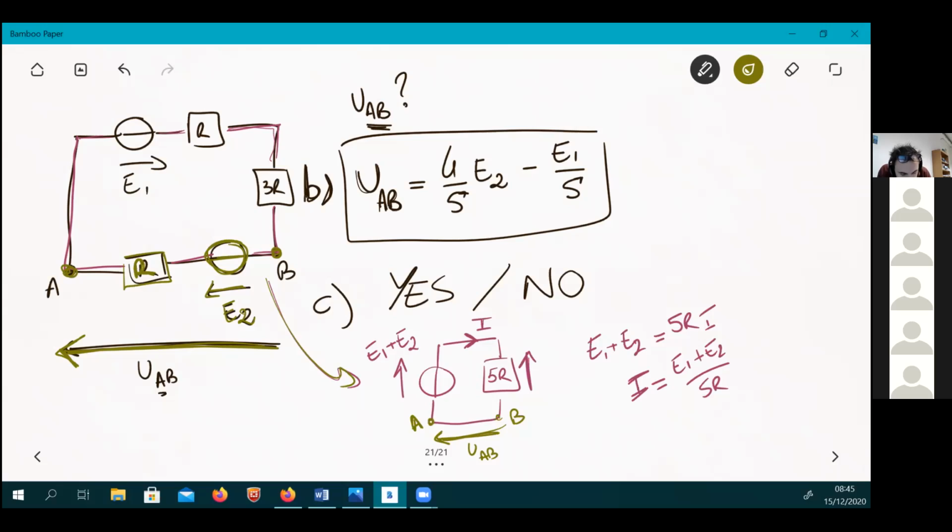So when you discuss currents in a single mesh, you see that all the things are in series, so this is not a problem simplifying your single mesh circuit. But when a specific voltage between 2 points is asked, and you have components between these 2 points, then you are not allowed to play with these components. If not, you of course are changing the voltage between the two terminals. Is it clear?